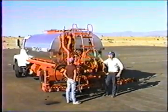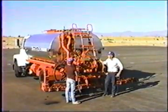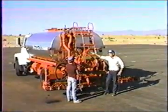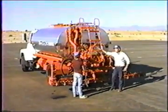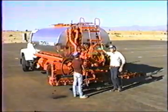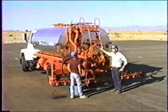Number 2, the chimney doesn't work right if you're going down the road, and it causes the burner to soot up fast. If you drive around for 2 hours with this burner running, your total heat tube will be sooted up to the point that it won't burn the next time. Then you'll be screaming at us because the burner doesn't work. And if you do it twice, then we put a switch on the truck that won't even let the burner run when you've got the brakes released.